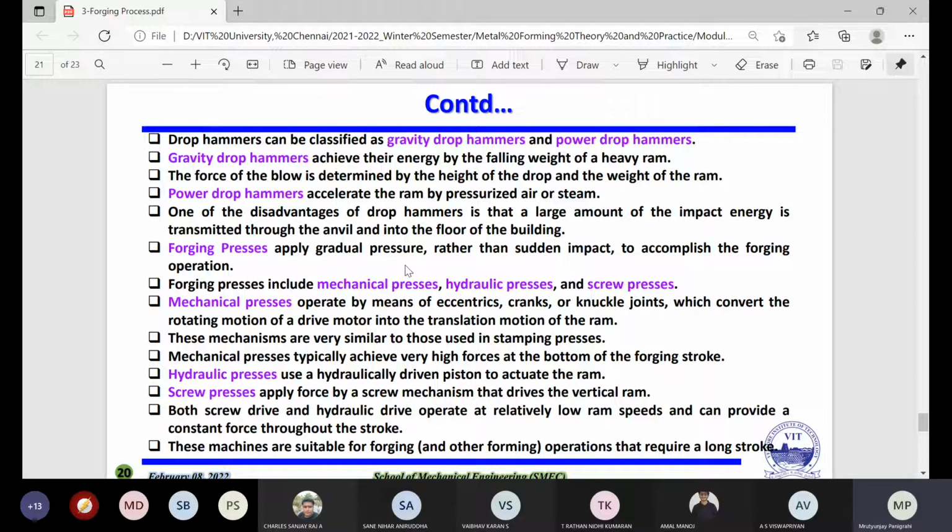But in a normal furnace, heating at 2 degrees C per minute, taking it to 1000 degrees C may take 4-5 hours, or even 7-8 hours. With the laser furnace, within 5 or 10 minutes you can reach 1000 or maybe 1200 degrees C, depending upon the furnace capacity. Another good thing is that it is precise. In a laser beam furnace there is a particular area, for example 10 centimeters by 10 centimeters, as your heat treatment zone.